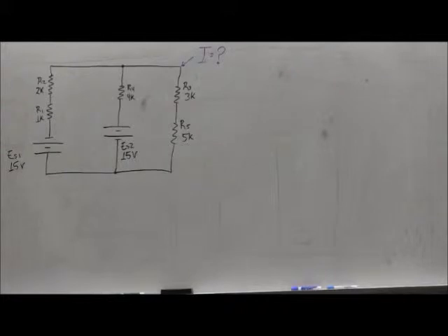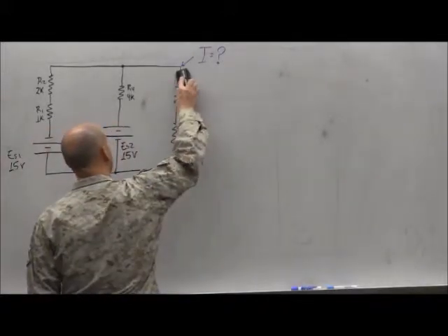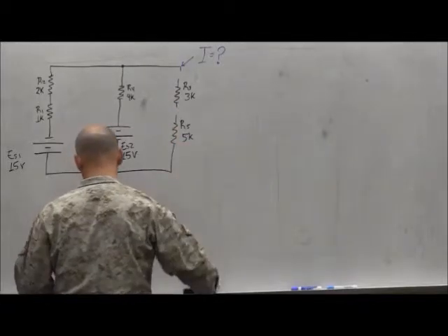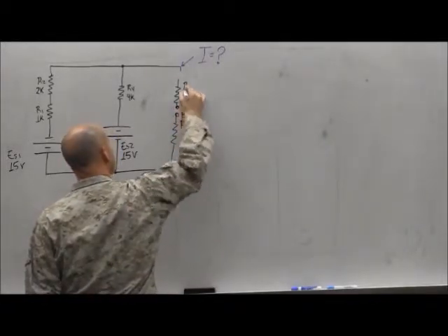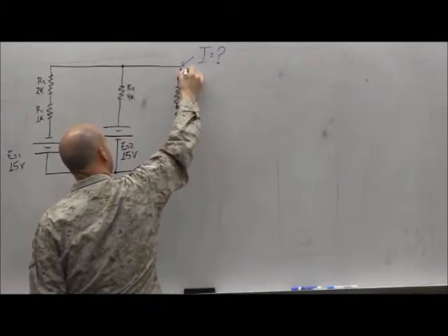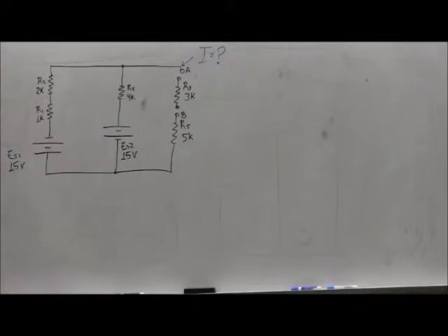All right, so let's go ahead and do that. What's the first thing we do with Thevenin's? Pull out the load. Okay? So we do that, we label A and B, right? Now what? Now we've got to go around the loop, right? Find the voltage drops.